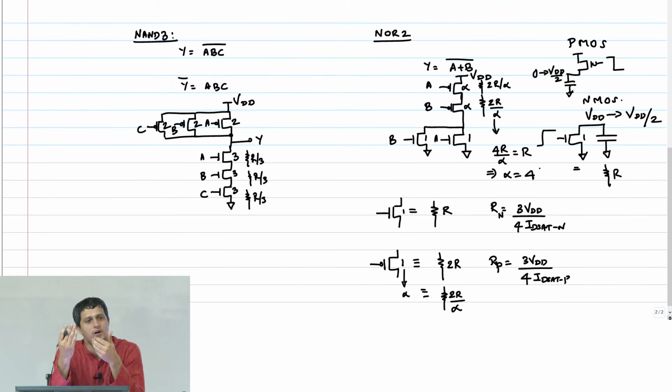So from the inverter, it's not surprising: if you stack transistors, you need to multiply the width by the stacking size, right. So unit inverter is 2, NOR 2 is 4, NOR 3 is 6 and so on. Any questions here?